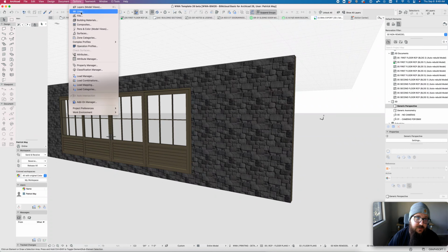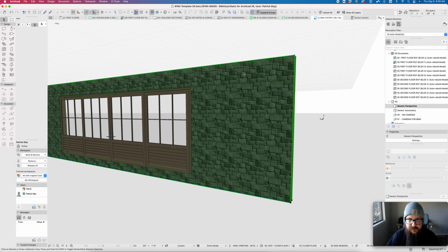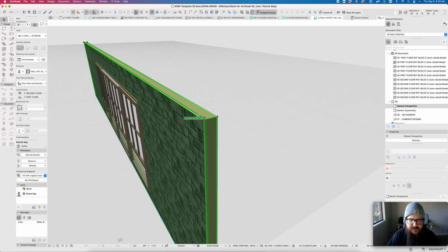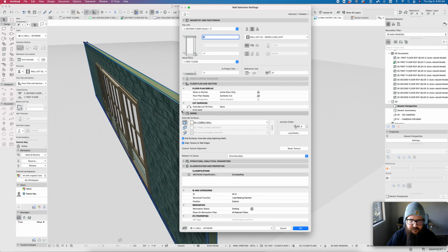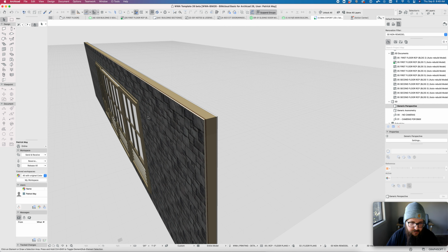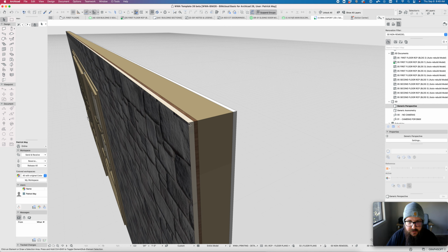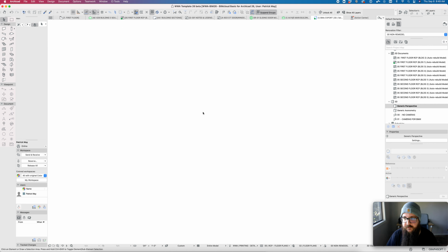Okay, having looked at lines, fills, and surfaces, now we can start looking at what things in ArchiCAD are actually made of, and generally speaking, that is building materials. The surface is basically just a skin that we use on the outer layer of these elements. It's this surface override in most element types. But the building materials, that's this sort of cut or material presence of things in ArchiCAD, is what graphically defines